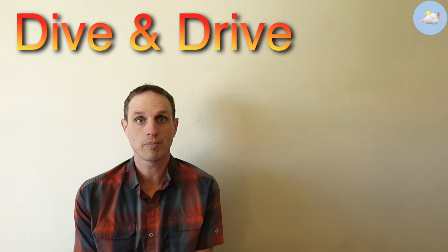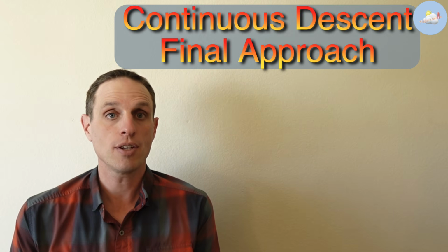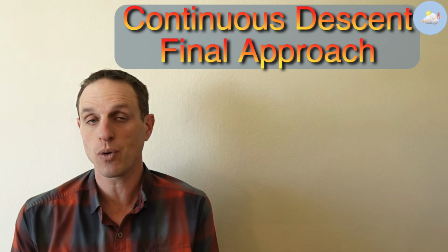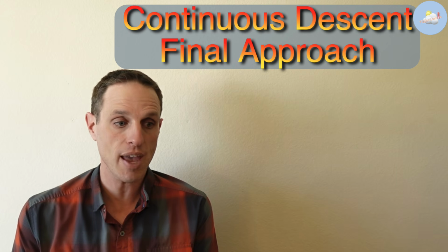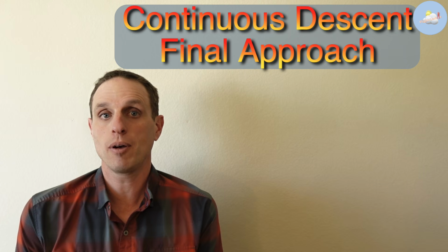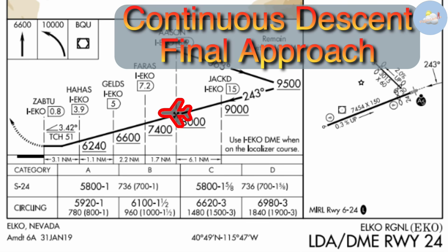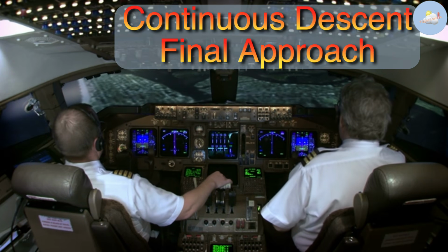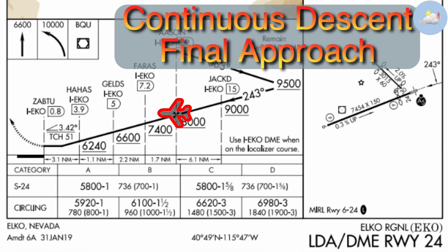of the approach. Years ago, the FAA and the National Transportation Safety Board began pushing what's called Continuous Descent Final Approach, or commonly called CDFA. And this is a wonderful concept. The benefit of it is once you pass the final approach fix, you essentially do a single configuration change of the airplane. You set the power and you set essentially a constant rate of descent.